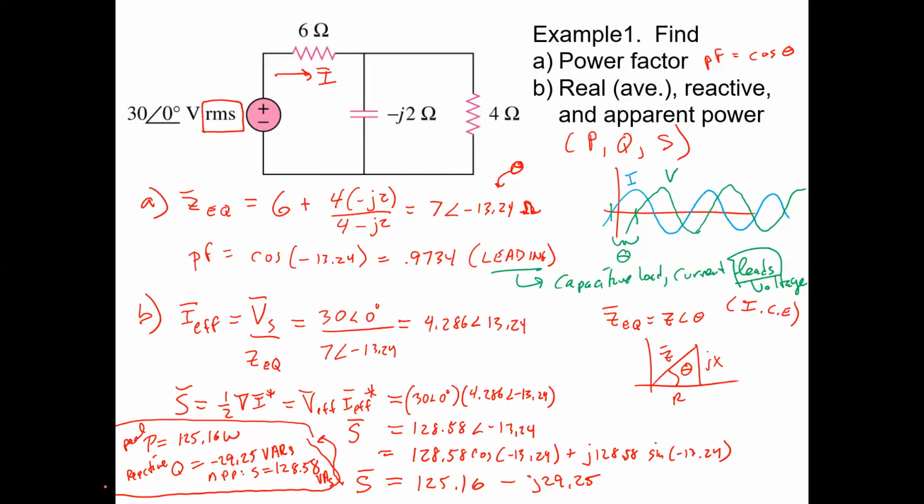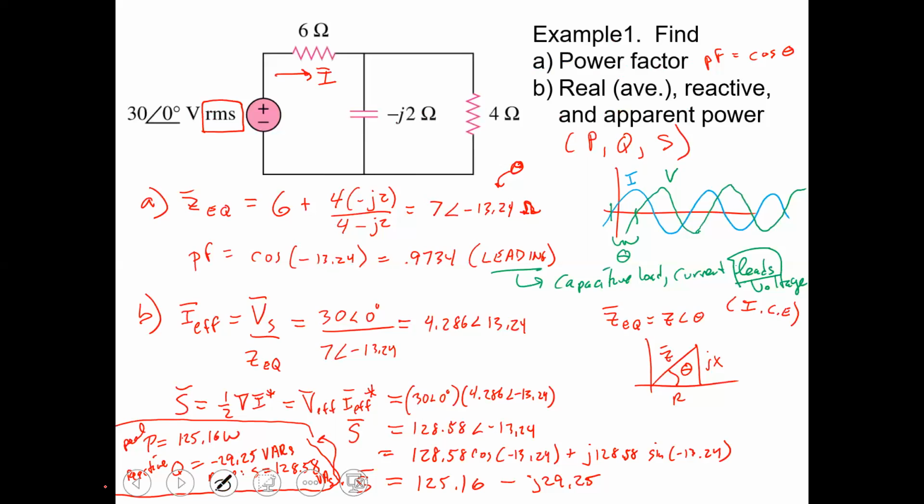Okay, so that's that. And another interesting thing we can do is maximum average power transfer. We talked about this, yeah, Mason? If we want it in terms of RMS, yeah, that would be the measure. Well, it's just a divide by 2. If you're given the voltage as a magnitude, then you'll find the current as a magnitude, and then the S is going to be 1/2 of V times I.